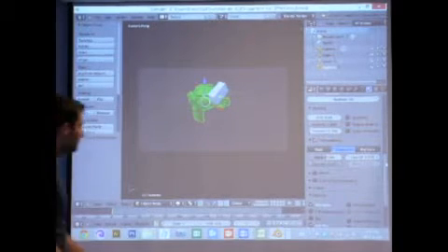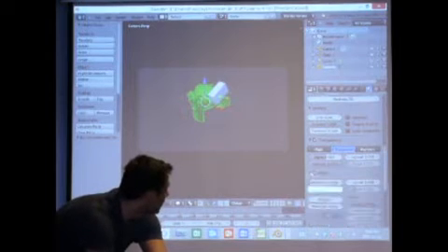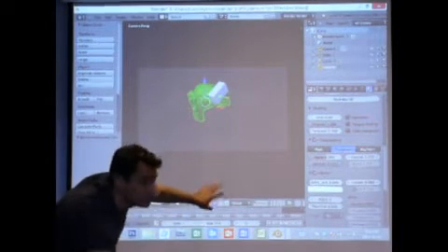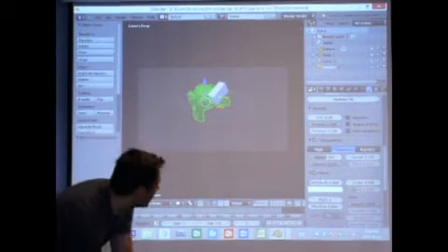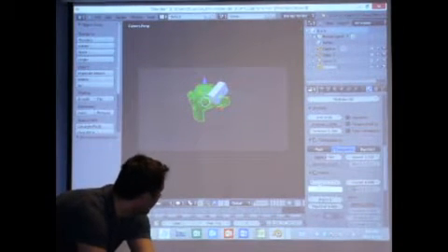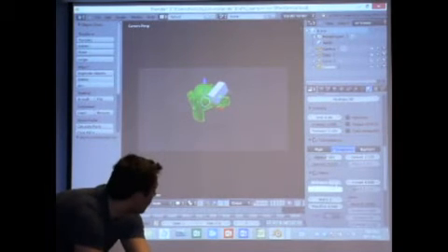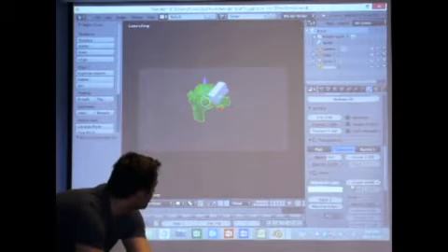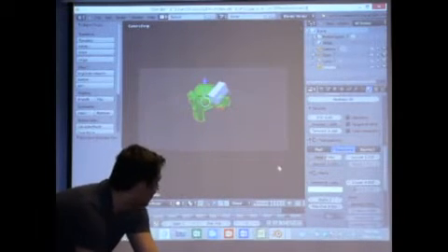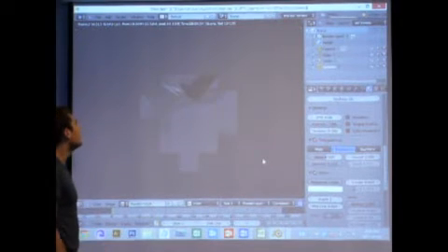Okay. So another thing you can do is add mirror, so just to add reflection. You can actually make it a perfect mirror. The reflectivity right now is 0, so it doesn't reflect any light. It just sort of scatters it. And if you change the reflectivity, actually the reflectivity goes up quite a bit. If you change it to 1, it will be a perfect mirror that will reflect gray all around. So if you see that, it will be very unexciting.